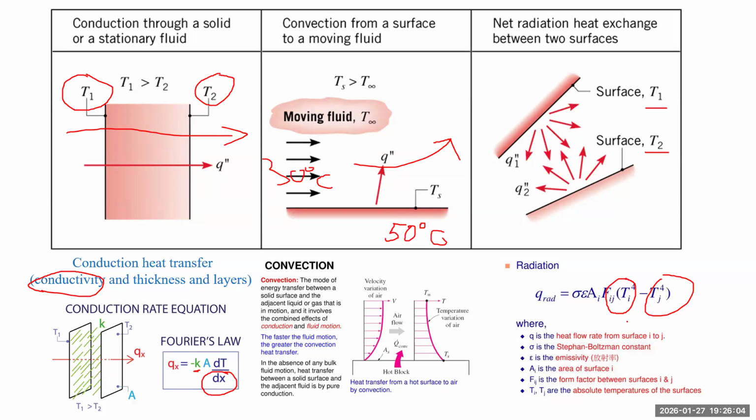If we introduce wind with good urban ventilation, good wind will also remove heat. And if your building has good thermal insulation, it can also block the outside heat flowing into your building. So these are the strategies we can consider.